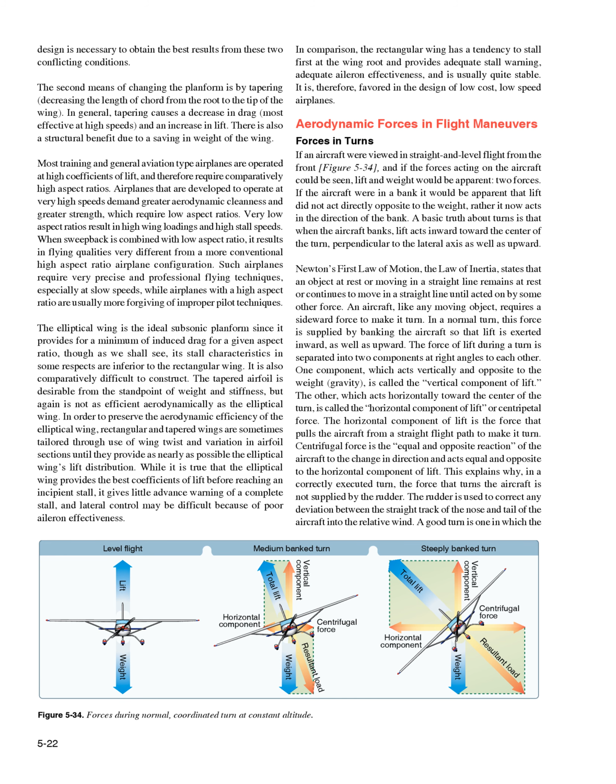Aerodynamic forces in flight maneuvers: forces in turns. If an aircraft were viewed in straight and level flight from the front, figure 5-34, and if the forces acting on the aircraft could be seen, lift and weight would be apparent, two forces. If the aircraft were in a bank, it would be apparent that lift did not act directly opposite to the weight, rather it now acts in the direction of the bank. A basic truth about turns is that when the aircraft banks, lift acts inward toward the center of the turn, perpendicular to the lateral axis as well as upward.